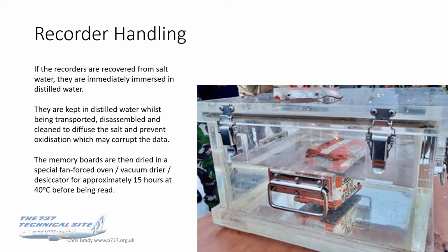Now, if the accident is at sea, then when the recorders are recovered, I've specified here salt water. It's particularly salt water, but I believe it also happens, as a matter of course, in fresh water as well. They're immediately immersed in distilled water, as you see in this photograph here. That's what that contains.